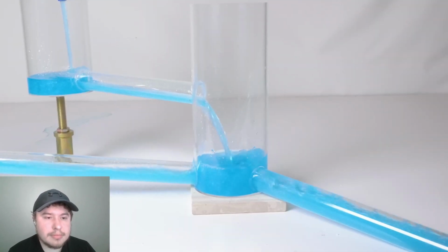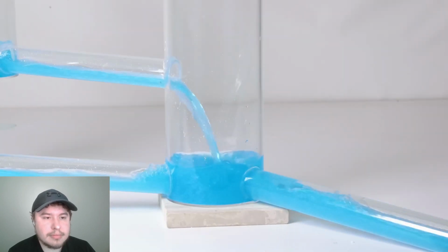Obviously, having raw sewage spilling to the surface is not optimal, and many cities in the US pay millions of dollars in fines and settlements to the EPA for the contamination caused by backups. Another thing this model shows is that not all pipes have to come in at the bottom. They call this a drop manhole when one of the inlets is a lot higher than the outlet.